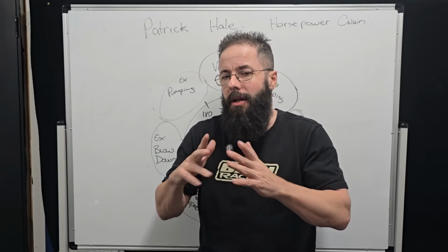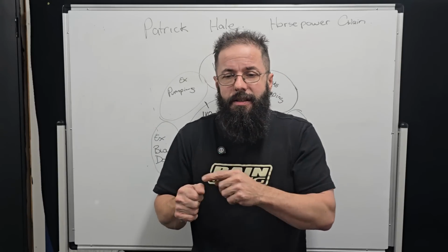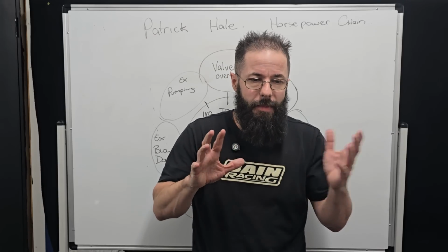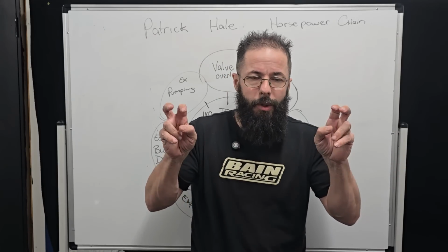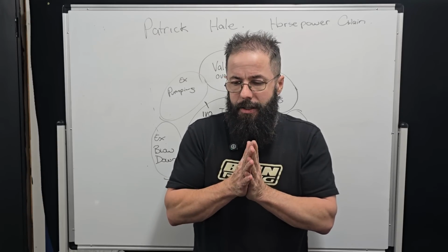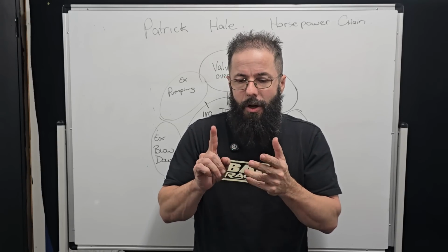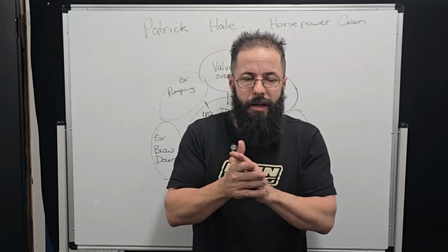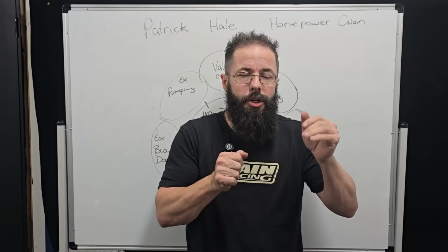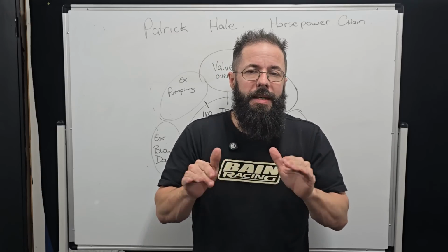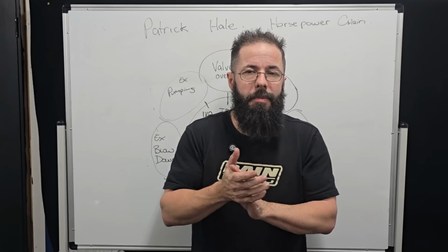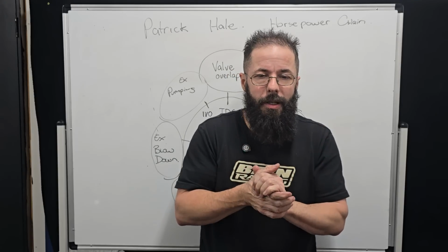So this is why I don't like a lot of camshafts, and in the next series we might get into different calculators that calculate what's the optimal cam timing. I think Dave Vizard's got one. There's a couple there we'll look at. If they're not taking into account velocity, inertia, and wave tuning, they're really missing the mark by 2, 3, 5 degrees even. So they can leave a lot of horsepower on the bench. So I want to talk about that as well as we get into it.